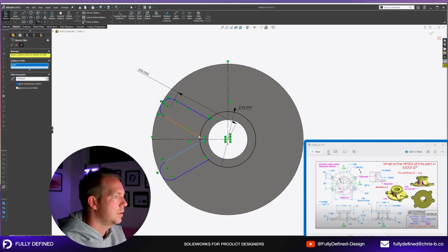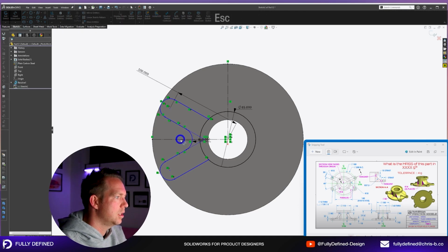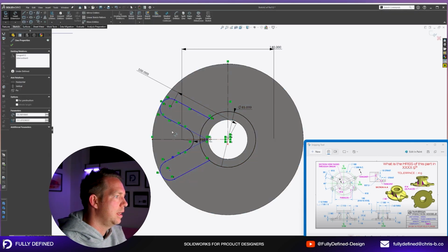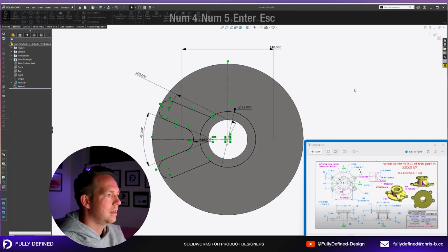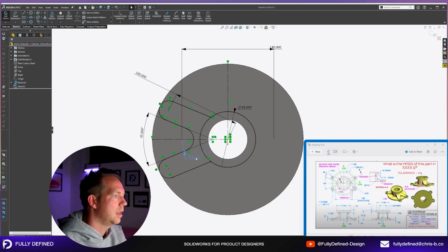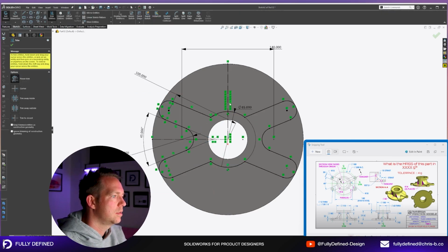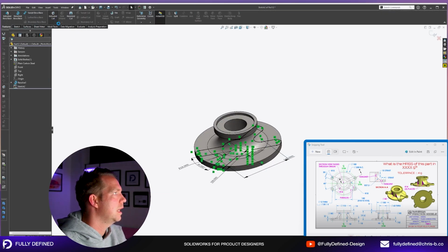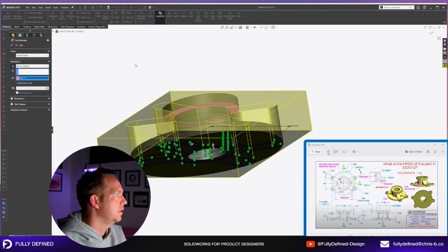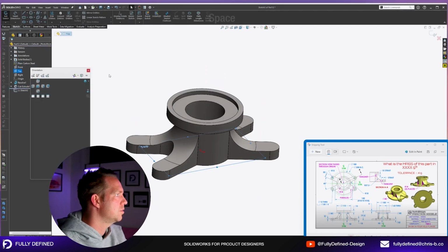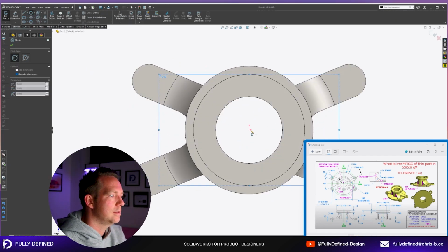I'm going to put a fillet in between these 2, 18, and dimension that center point of that fillet, 140. Once we put that in and our angle, that sketch is fully defined. All right, that might have been quick, but you can always slow down on replay. All right, now I'm going to mirror, trim away the insides, because then what I can do is an extruded cut up to this surface, flipping the side to cut, and then I've got my general shape. All right, I think that's the trickiest part of the whole model, getting that sketch right.